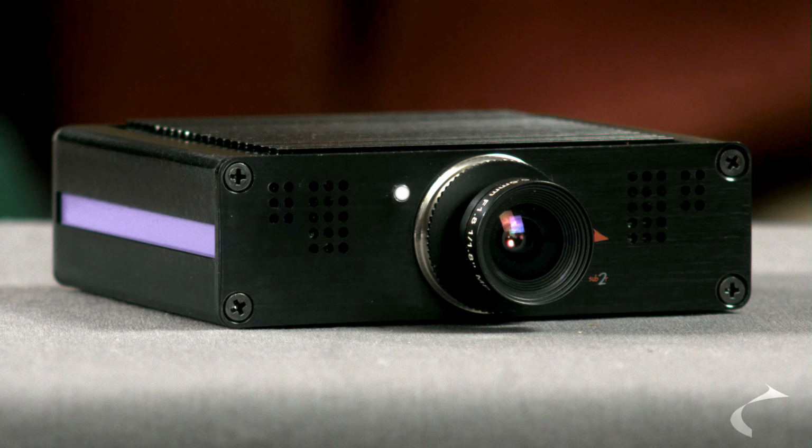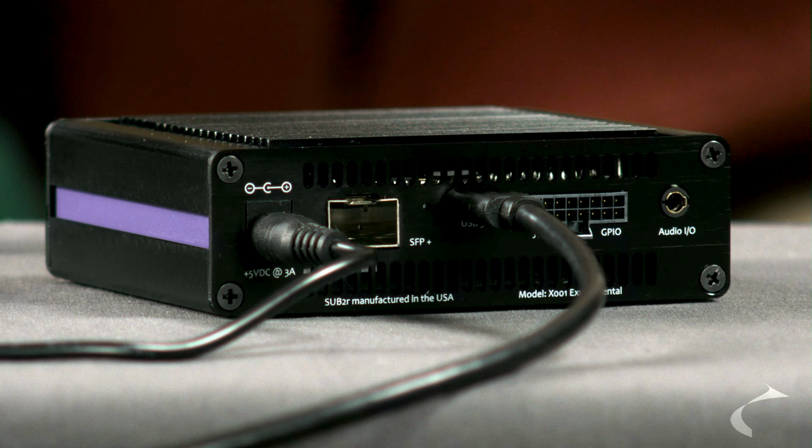If the LED light turns from white to green but picture freezes in a few seconds, this means that either the USB port does not have enough power to sustain constant supply, or that it is internally shared with some other ports that have devices already connected to them. In our testing, we have come across examples of motherboards where supposedly an isolated USB port was indeed shared with other and therefore limited data throughput and power allowance.